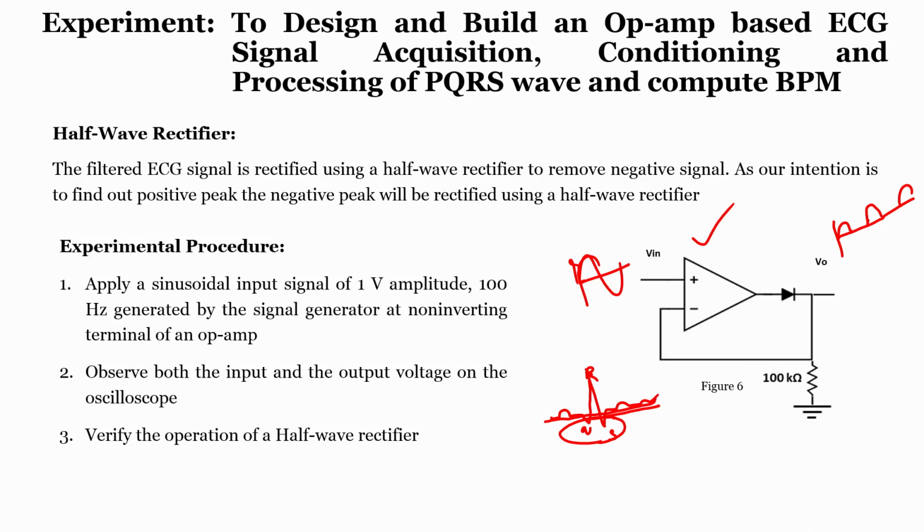So, it is easy to understand the highest peak in an AC signal. What I mean is, suppose I pass the signal to a capacitor, since the maximum voltage is at this particular value, and if I do not create any discharging path, the capacitor will always stay at this particular point. But how do we set a threshold?